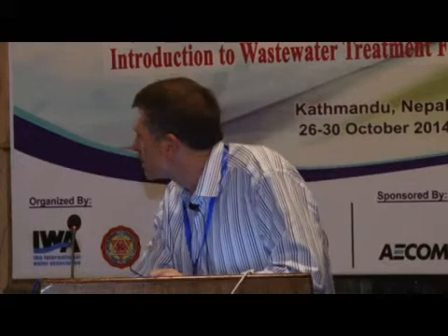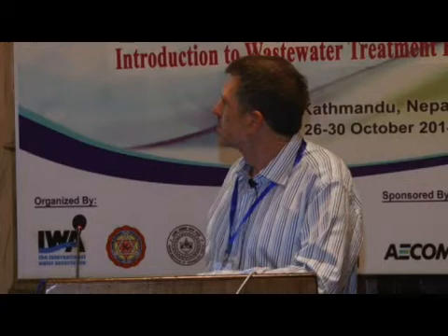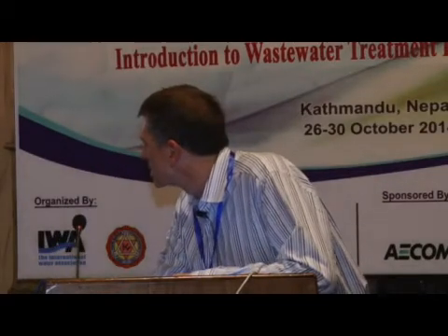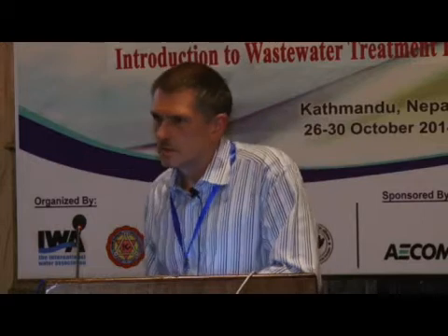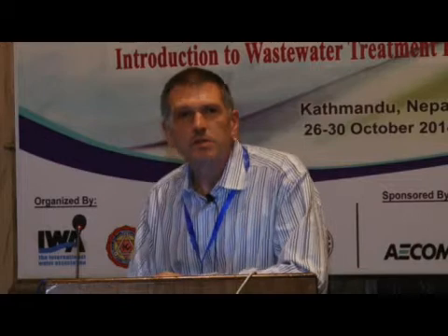And we see a lot of nitrate. 29 milligrams of nitrate. For phosphorus, there was something like 7, if I remember correctly, 7 milligrams in the influent. And then what's coming out here is 4.1. So I guess the 3 milligrams that you mentioned, Krishna, is about right in this case. Or we made a model such that it will be right to what Krishna says.